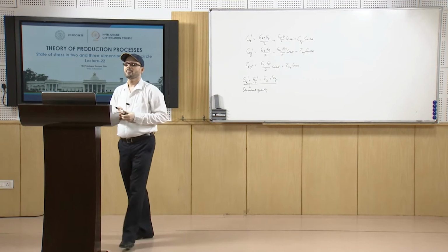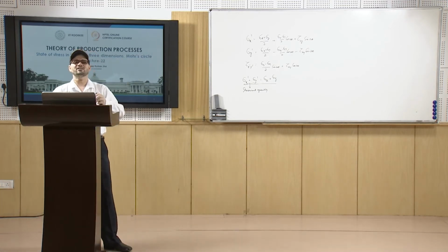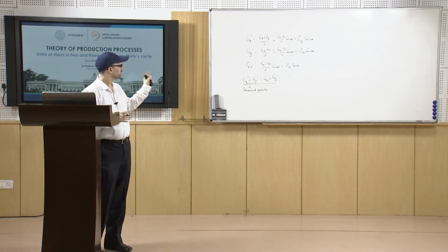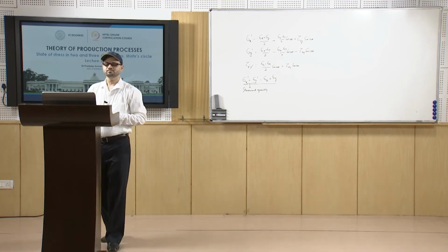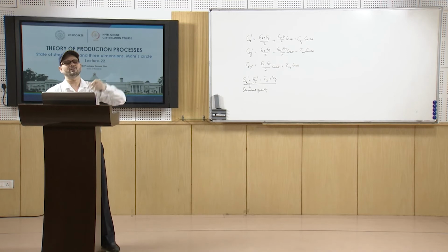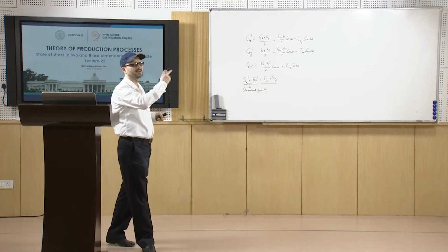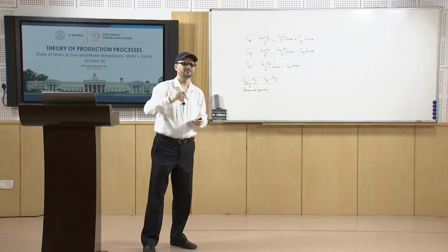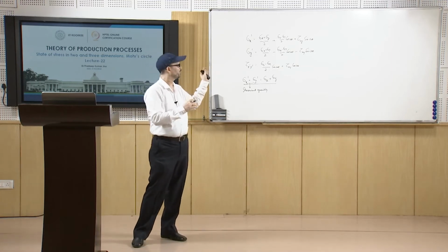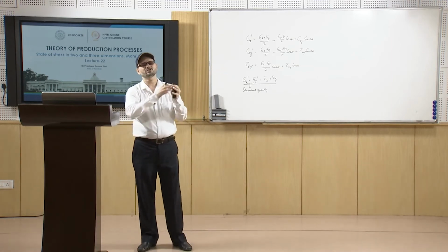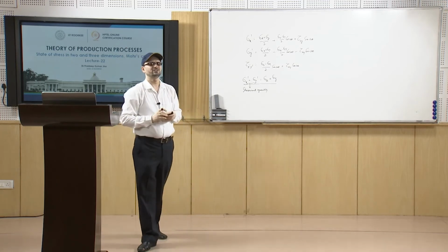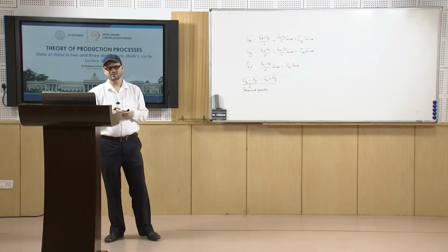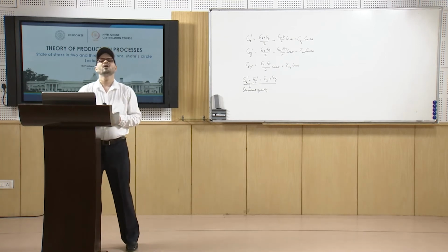The variation of normal and shear stresses forms a sine wave with a period of 180°, because it is going 2 theta, which encompasses 360°. After 180° it repeats itself, so it has a period of 180°.